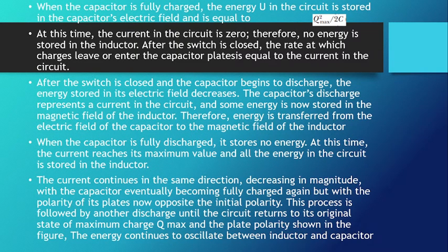The current flow in the LC circuit is shaped like a sine curve. In the next 1/4 of the time period, the current of the capacitor starts to decrease, resulting in another change in current. At the end of the capacitor discharge, if you check the EMF across the inductor, it will have the opposite polarity to the initial EMF. This reverse EMF charges the capacitor with the opposite polarity.